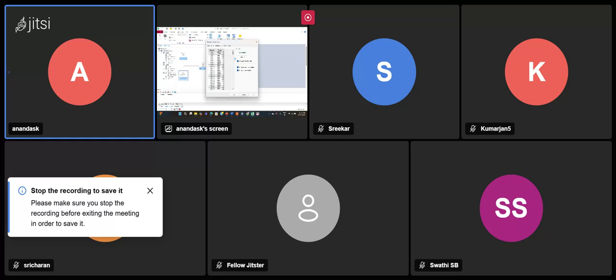If you're working on a specific node, you should know which CAN channel your node is connecting to. So the source and the target you should give here. For example, in the vehicle it is CAN channel 2, and here also you should give 2, and then you should give OK.